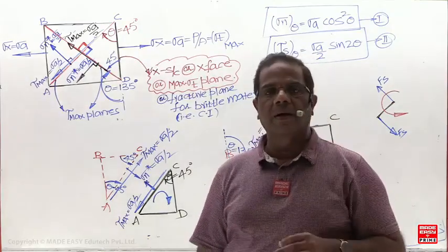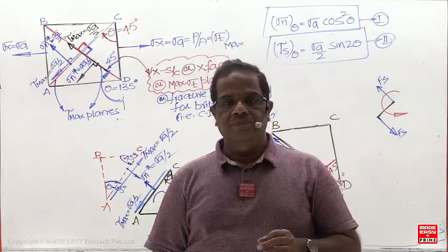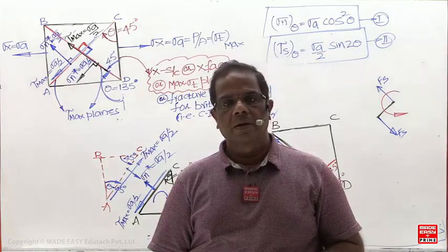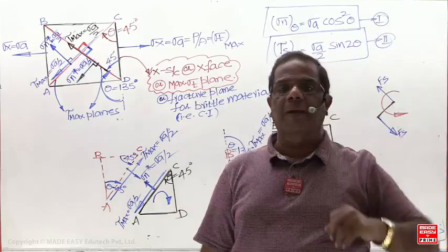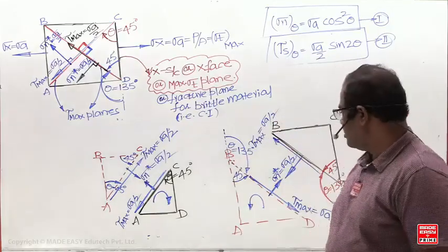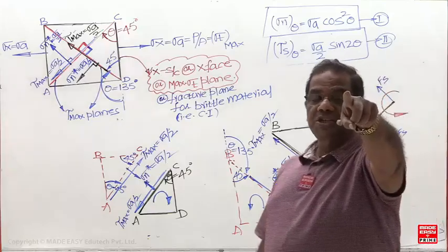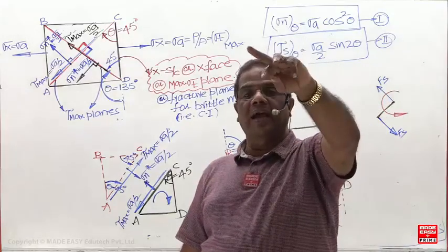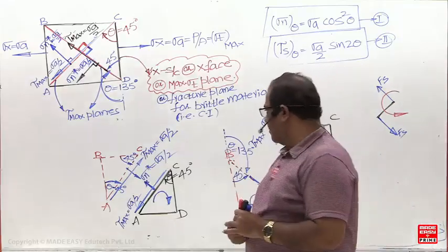This is very important now. Whenever a shear stress is there, there is a complementary shear stress. Complementary means on a perpendicular plane. Always on two mutually perpendicular planes, shear stress values are equal, unlike. But what about the normal stress values now?